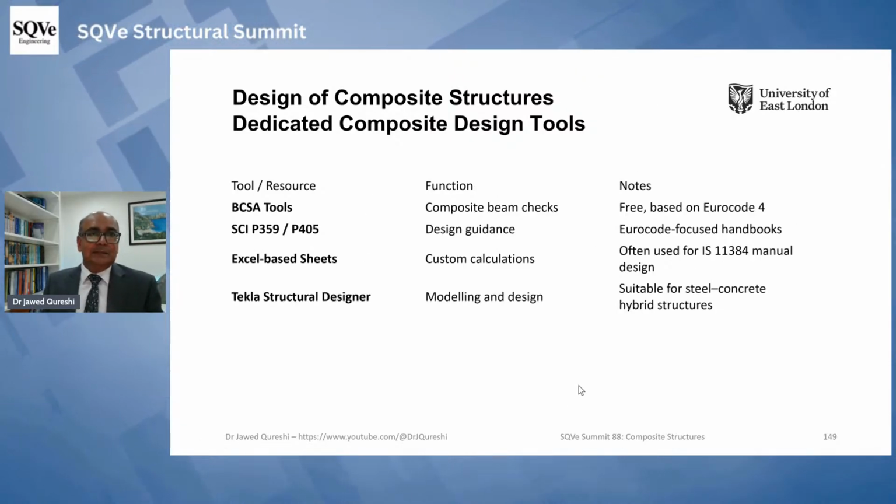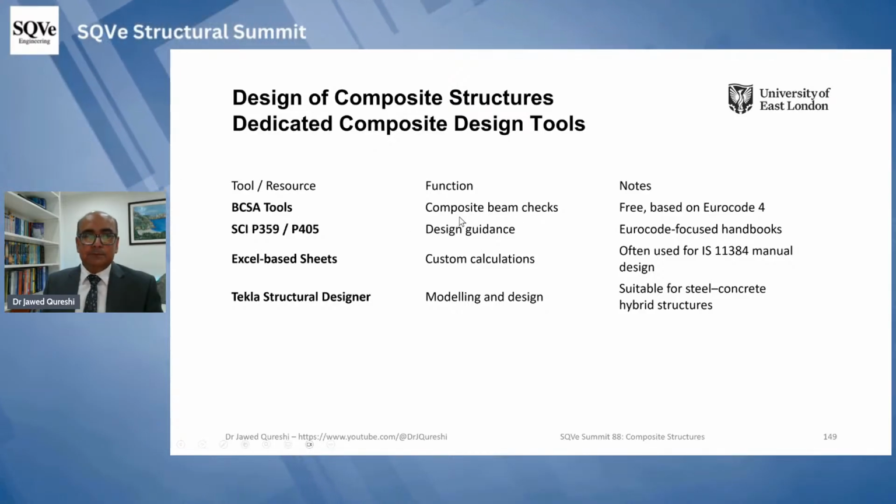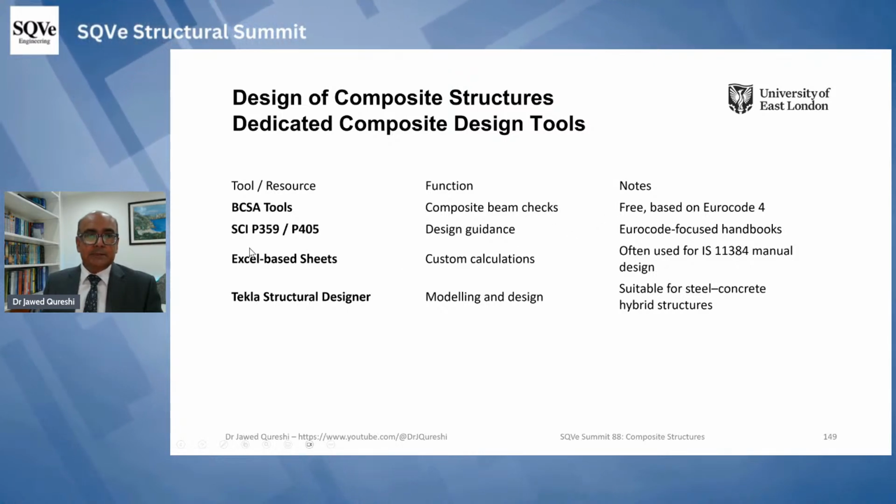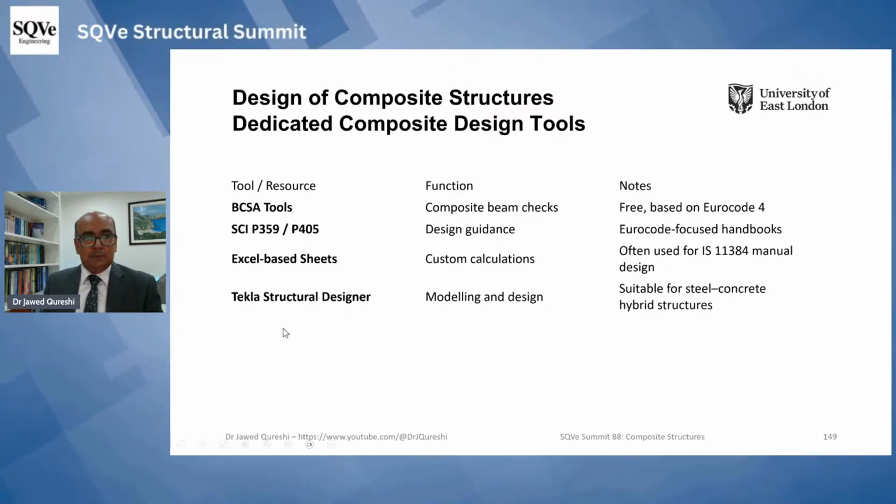And design tools, I find these BCSA tools, British tools for composite beam checks, very useful. And Steel Construction Institute guides, Excel-based sheets, which can incorporate Indian codes. Tekla Designer, it has got something as well.